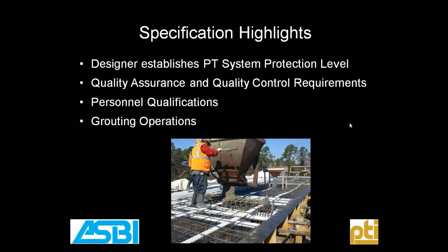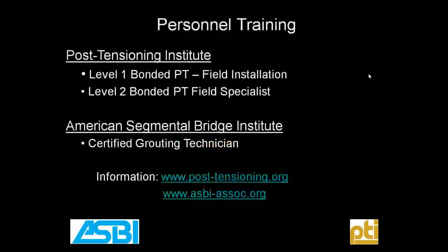There are personnel qualifications that are required not only for the installer but for the grouter. And grouting operations are also covered, and I know that's something that many owners have concerns about, but the grouting is now covered within that specification. It does reference the Post-Tensioning Institute's grouting specifications for the material specifications and installation of the grouts.